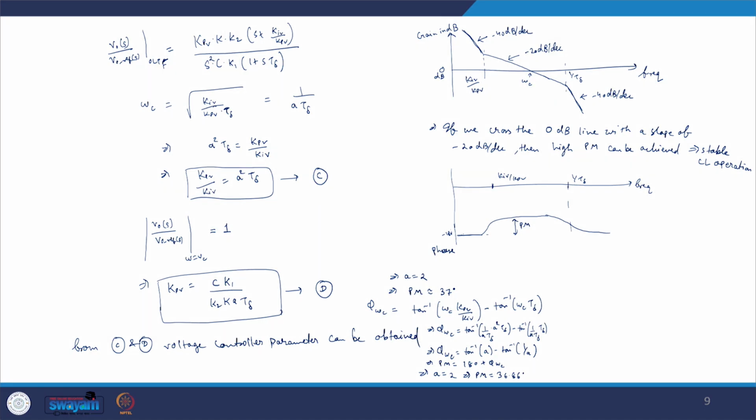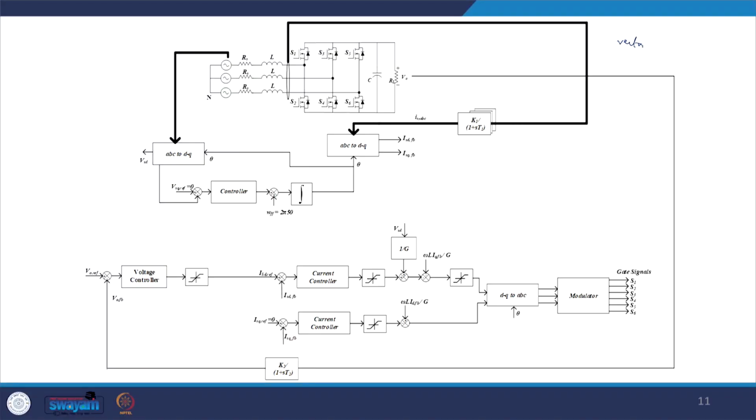and that's when we can design our closed loop control. So let us see how we will make our entire closed loop using this independent control method, going into the DQ model and doing ABC, and we are making the IS space vector lie along the VS space vector. Since we are controlling the angle as well as the amplitude of the vector, this is also called the vector control approach, or the vector control of a 3-phase AC to DC converter.